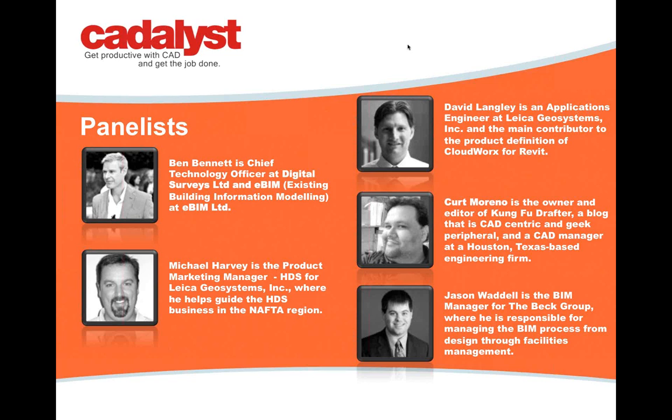However, I have a W520 laptop, and I can make it run just fine. It has a regular processor on there. It has 8 gigs of RAM with an NVIDIA Quadro 1000M video card. So something like that or better certainly will help, but it doesn't need to be anything super special. So basically, any workstation that would run Revit otherwise should be suitable for running these large point clouds through CloudWorks inside of Revit. Exactly. Yeah, definitely.